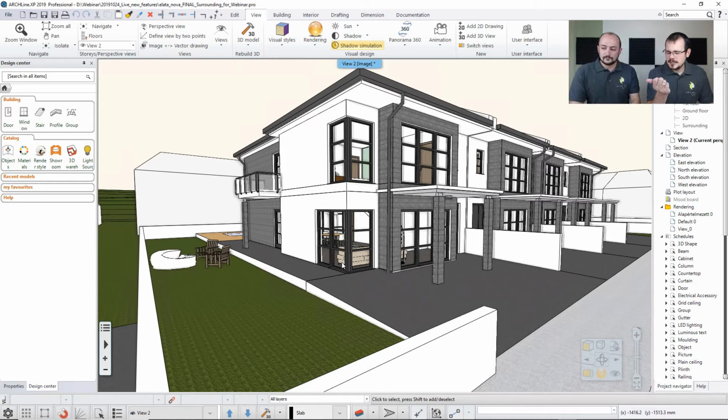So we have the 3D, we have the materials, and we have the light sources. What else? Well, perspective views, for example. During designing this model, I already added a few views, and this is very likely to do because it is very easy to communicate that way. And when you would like to find all your views, you can either click on this little perspective eye, or you can click here in the 3D.